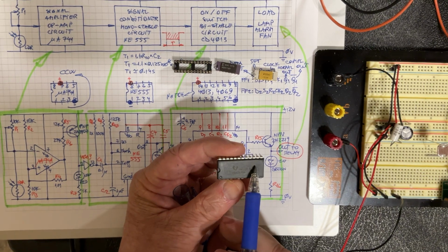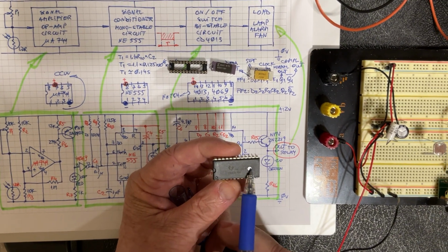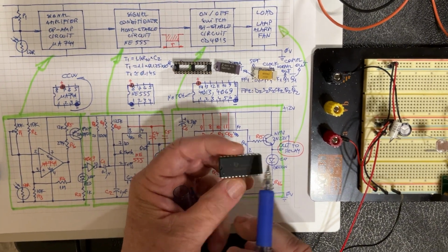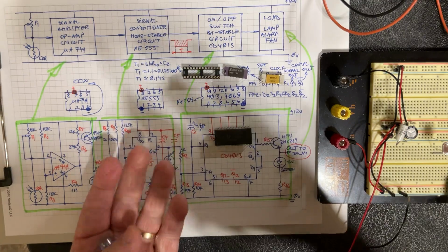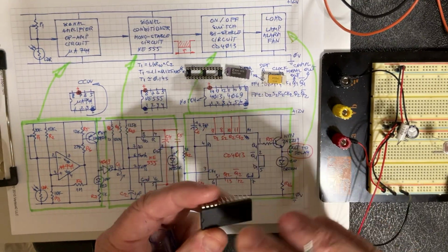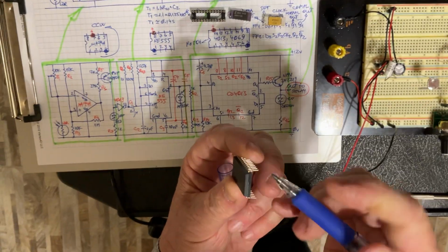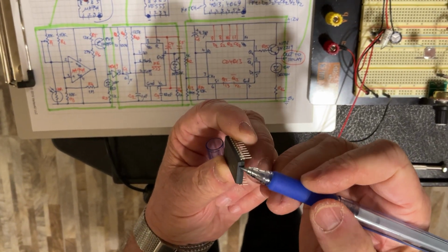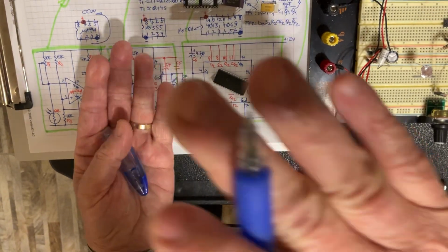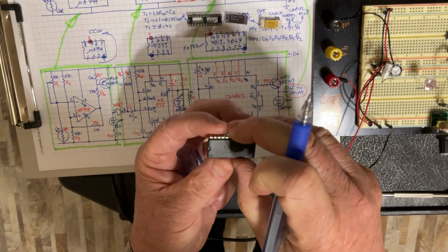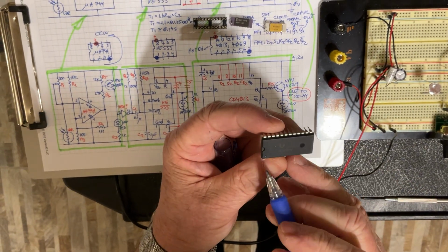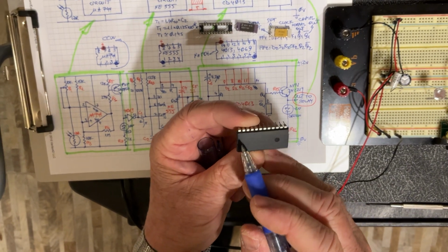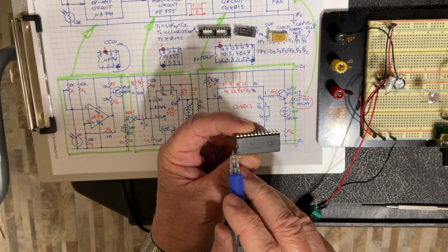Don't consider this big dot, which is exactly symmetrical versus the two sides, because this is only from the press putting the two pieces of plastic together, the top and the bottom. You can see there is a little edge right here in the middle, because they put the two pieces of plastic together to cover the semiconductor, which is somewhere inside. But you have to consider this dot, which is above pin 1, or the notch, showing you that pin 1 is on the bottom left of that notch.